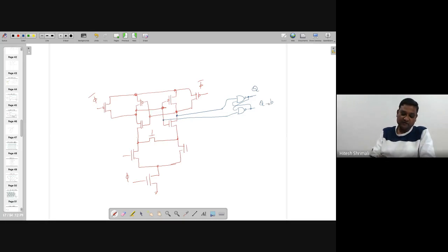So if you remember previously we studied this one, and here delta V is going to be fed. If this delta V is positive, meaning this terminal is positive and this terminal is negative, then accordingly you will have digital logic 1 at the output, because it's acting as a comparator, and in this particular application we are going to call it a sense amplifier.